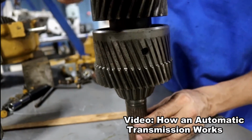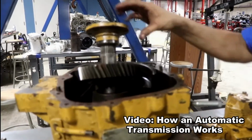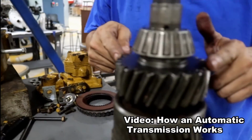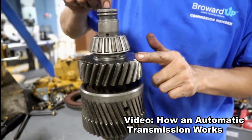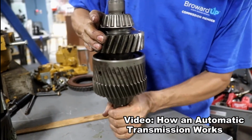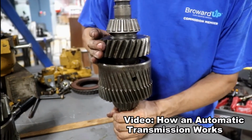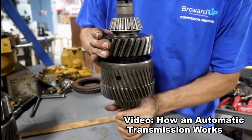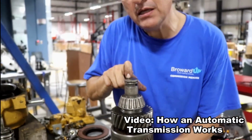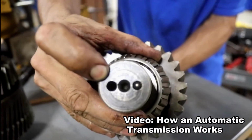At this moment, this is the gear on the input shaft that engages with the gear of the output shaft with the coupling. This gear engages with this gear. At this moment, because fluid is not entering here, the input shaft is not engaged with the output shaft. The output shaft is stationary because I don't have fluid pressure at the input. I don't have fluid entering at high pressure over there.